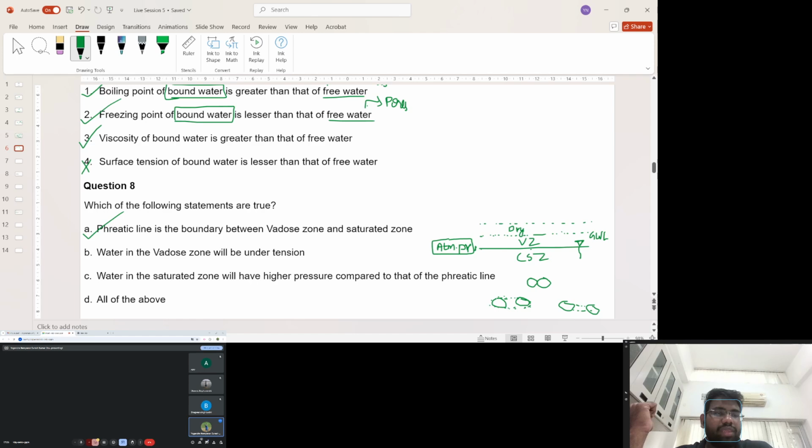So that is why, since you are exposed to effective stress problems now, the pore pressure above the groundwater level is negative. That is the sign convention which we use for compression and tension. Tension we consider as negative, and compression we consider as positive as far as soil mechanics is concerned, and in that pore pressure is considered, which is slightly different to what you are usually exposed to in strength of materials and solid mechanics, right? So this statement is also right.